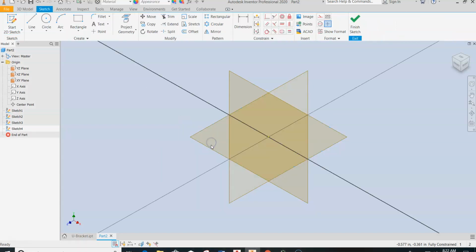When I create a new sketch, the sketch plane did not just automatically orient back to the isometric view, so it didn't turn around like it normally would. When we turned off the setting for look at sketch plane on sketch creation, the sketch will now stay in the isometric view.